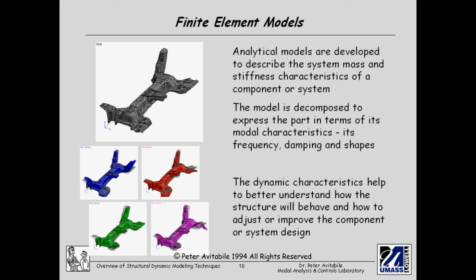But the same thing we do is we take this analytical model, we do an eigensolution on it, we basically decompose it into its dynamic characteristics, which is its frequency, damping, and mode shapes. Now these dynamic characteristics help us to better understand how the structure will deform when loads are applied, and will help us to make a better design.